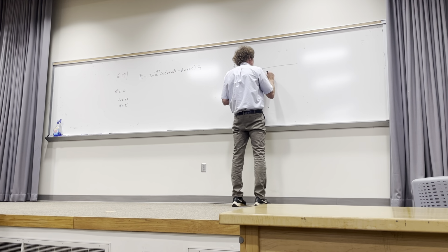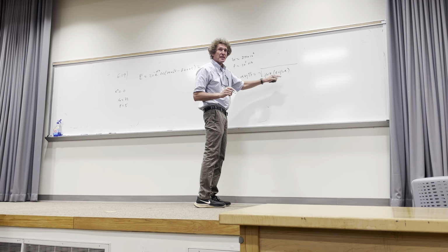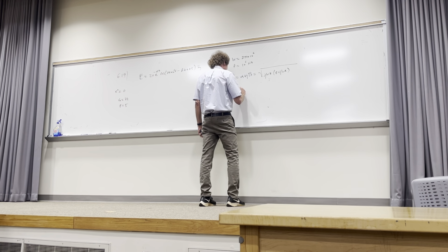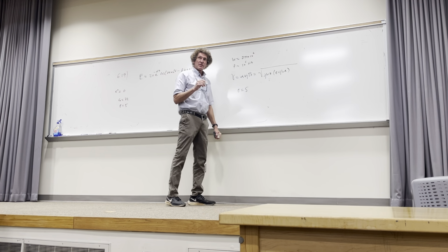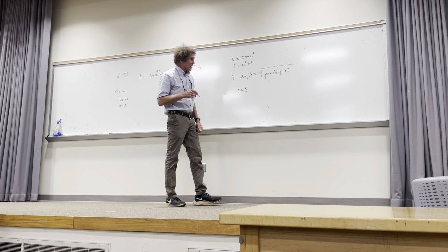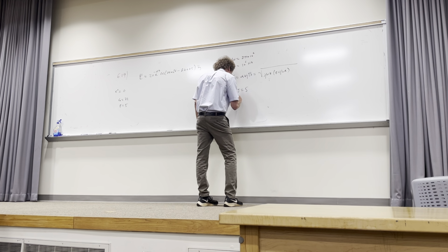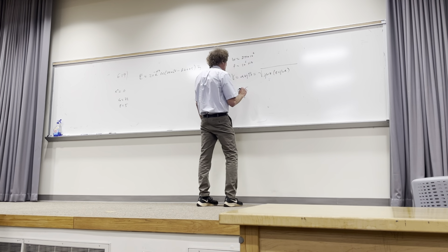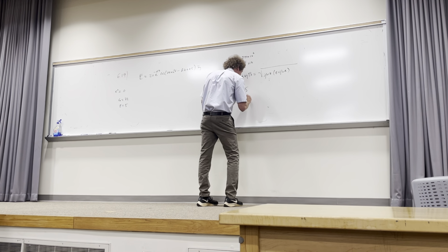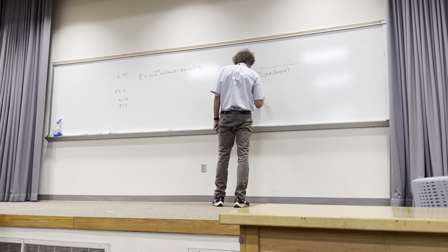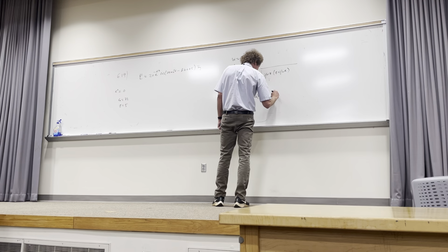So I want you to take a look at these two terms, sigma and omega epsilon. So sigma has a value given as 5, right? That'd be Siemens per meter, 1 over ohm meters. And now, what is omega epsilon equal to? Well, omega is 2 pi times 10 to the 6. Here, I have to multiply by epsilon, which is going to be 72 times epsilon naught. And epsilon naught can be given as 1 over 36 pi times 10 to the minus 9.